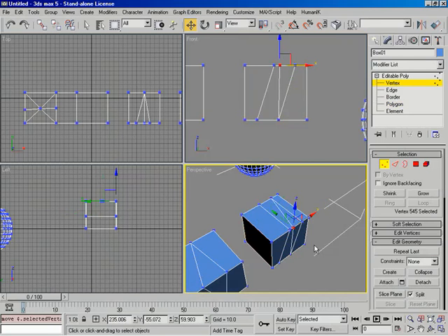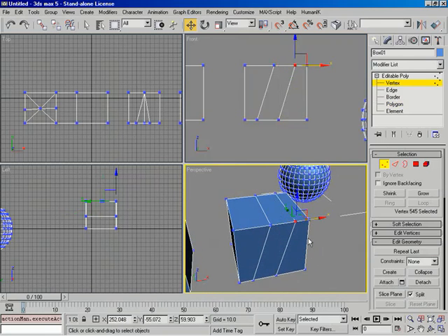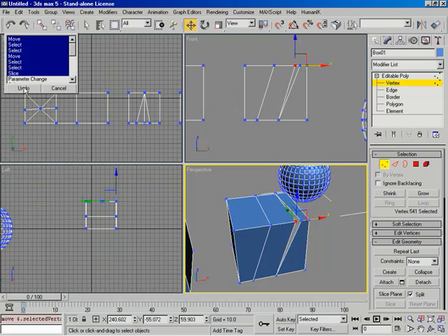Remember what happens. If you see that happening right there, no, it's not the fact that a polygon was added. Let's undo. It's the fact that you're pulling it the wrong way. So we'll pull that one out that way and this one out this way. So we did indeed make another incision into our geometry. Very cool. Okay, so let's go ahead and come up here, right click, and go all the way back before the slice.